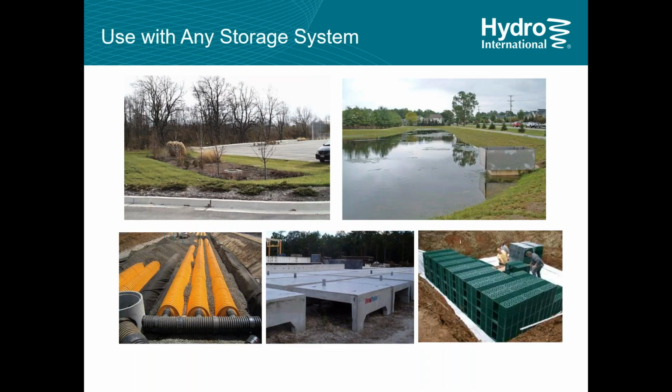You can use a vortex valve with just about any storage system, whether it be above ground or below ground, proprietary system, tanks, StormTech, ADS, StormTech chambers. It really doesn't matter what the storage system is, the vortex valves can be used with them.